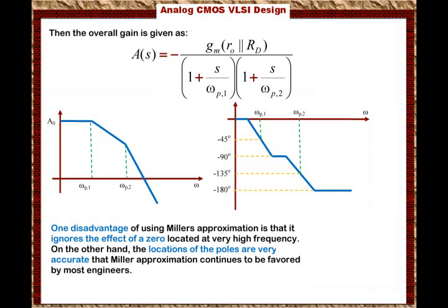The signal is amplified. Otherwise it oscillates, and we're going to dedicate a chapter to oscillators and how we can create a circuit that will oscillate later on in this course. But it is crucial for us to understand the frequency response of the system, not just because the gain attenuates as the frequency increases, but also because we want to make sure that the amplifier is stable.